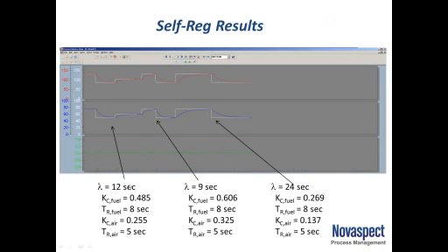When I chose a lambda of 12 seconds, I took a step down and I showed you that the fuel to air ratio held good and we got there in a predictable amount of time. I'm just showing you a couple examples of a faster or slower choice of lambda. The consequence is the reset time never changes. It's always the manual mode time constant. All we change is the gain.